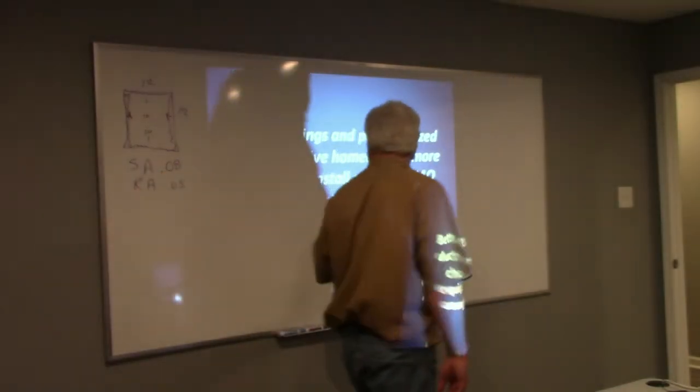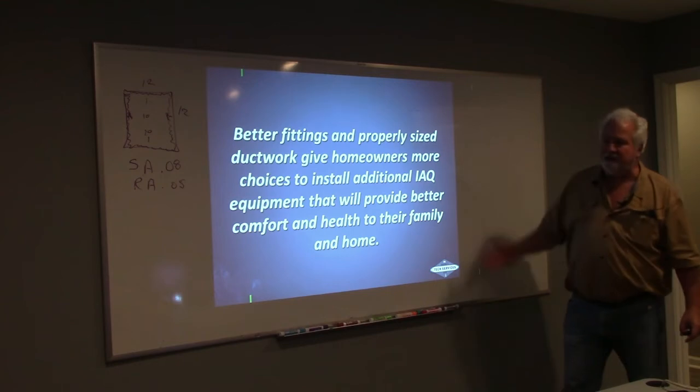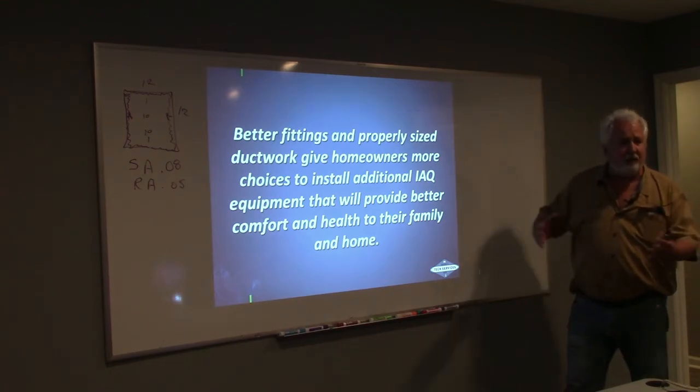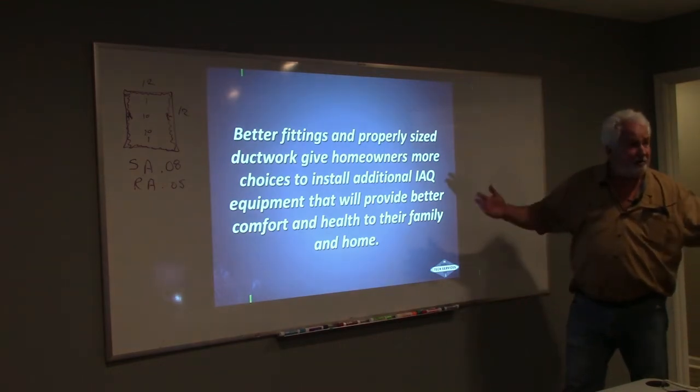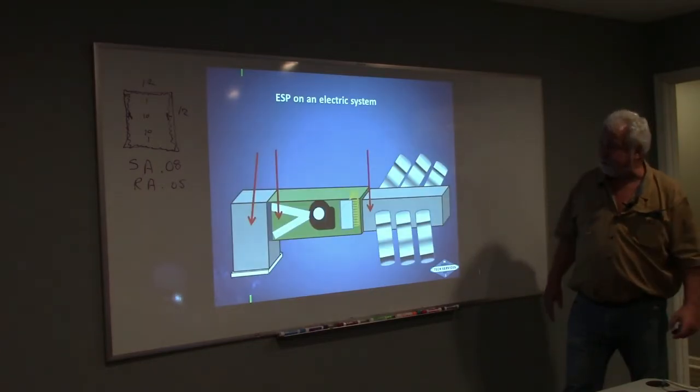Better fittings and properly sized ductwork give the homeowner more choices to install additional IEQ, because the more IEQ pieces I put in there, the more resistance I've got. So if I get the ductwork right, I can add some IEQ devices too.